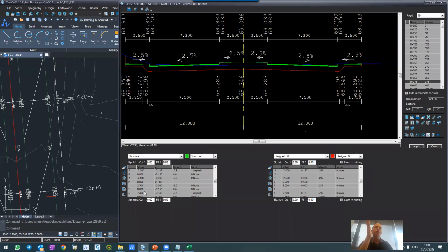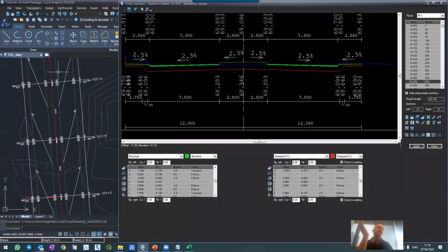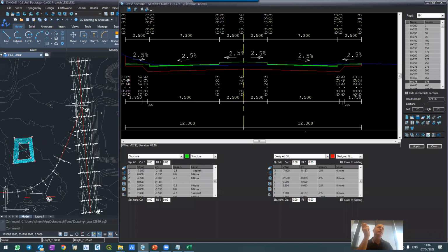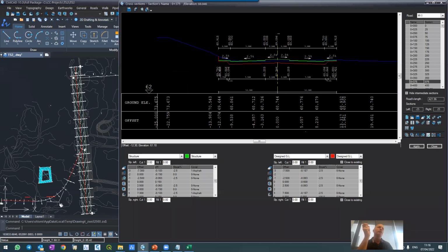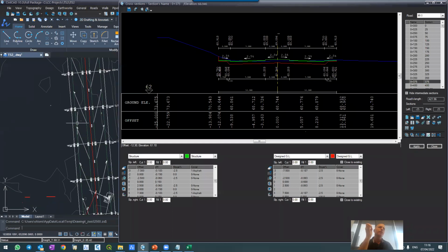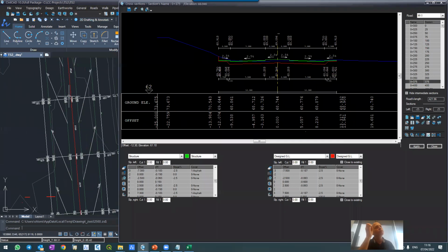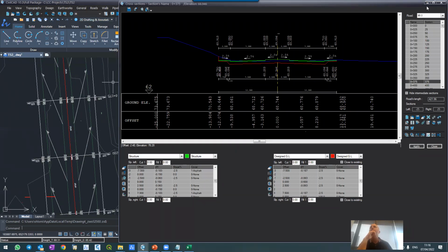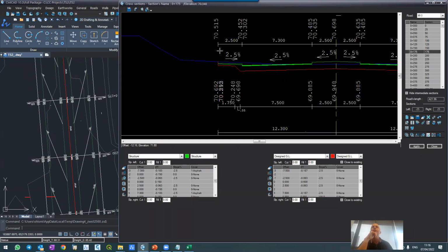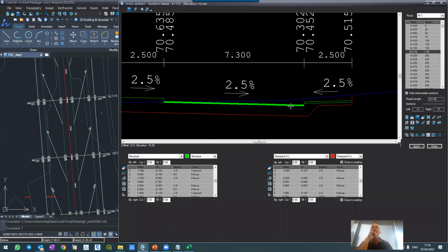So before I continue to the ditch, I'm answering a question: how to change the width of the road, or to deal with a road whose width changes. So let's assume that before the ramp, the road is widened from this section, from section 0.175. So I'm going to 1.75. And what I want to do is, on the right, sorry, on the right, I'm going to widen it from 7.3 to 8.3.